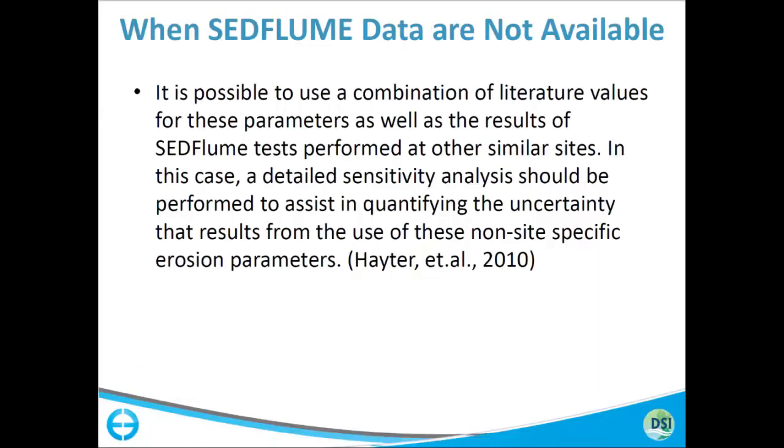So, quoting Earl, if you don't have it, you can use literature values and estimate and build up SEDFLUME data. I don't think that this is always necessarily the way to do it. If you have a site that you have a lot at stake on, like a sediment remediation, which are always in the near billions of dollars, well, you better have some real SEDFLUME data.